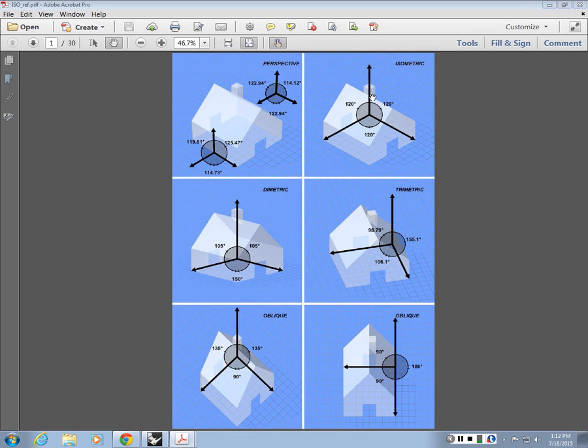But when it's in parallel projection, we actually don't converge these geometry edges to the viewer. We instead project them in parallel, or let's say perpendicularly to the viewport. So this is the view plane, and we just draft them as is. So that's how you don't get any distortion, and you will actually get the same measurement for these edges, right?